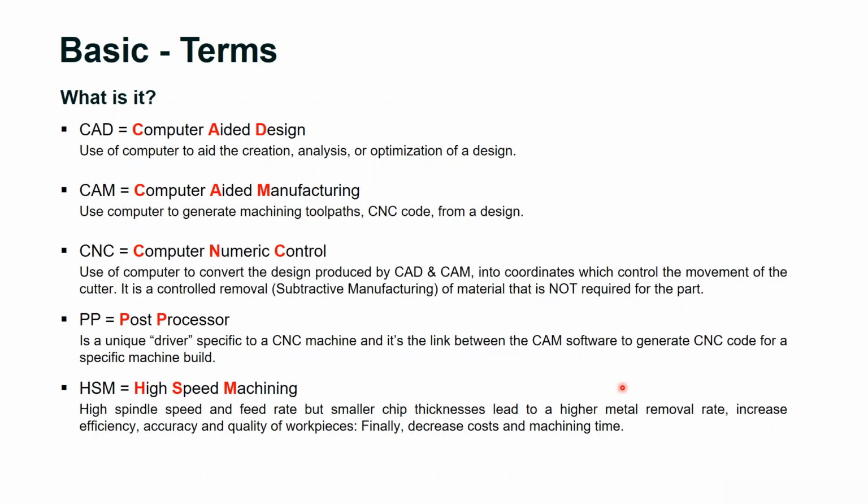HSM is the name of our software, and it also stands for high-speed machining. We try to keep the spindle speed as high as needed and also to increase the feed rate in the machine. By that we can remove material as quickly as possible and also get as good a surface finish on the produced part as possible.